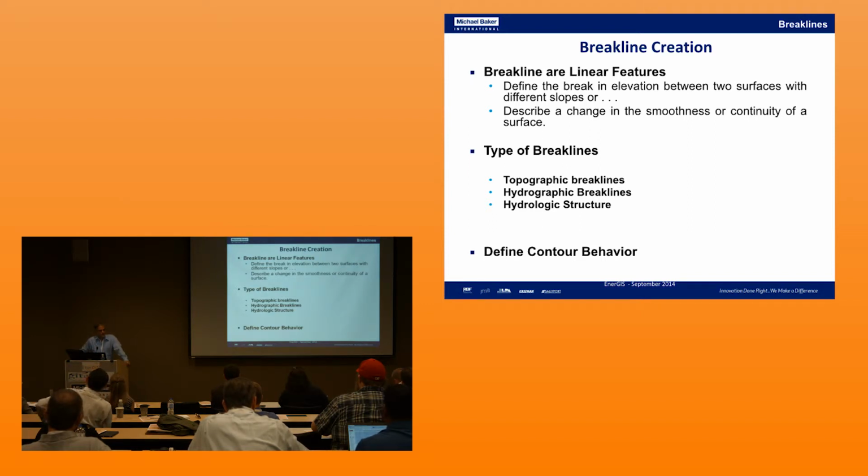For example, in the case of FEMA-related applications, especially if the data is going to be used for floodplain analysis and modeling, then naturally you definitely need to collect the breaklines corresponding to hydrographic and hydrologic structures. And if the data is going to be used more towards transportation or design-level applications, then obviously you need to collect the topographic breaklines also.